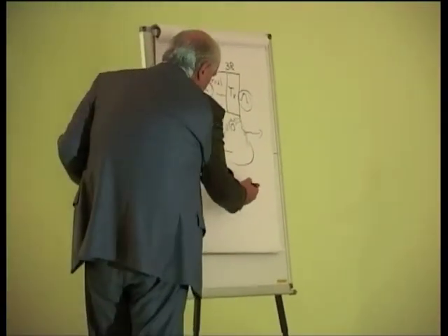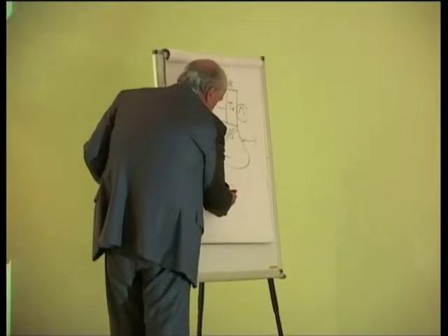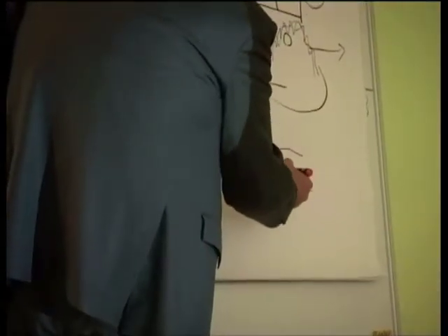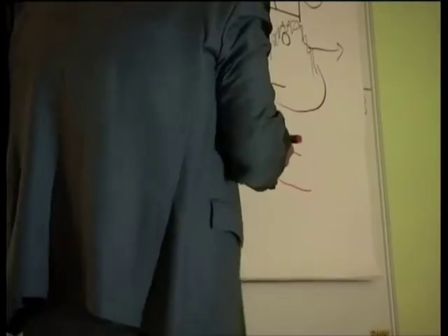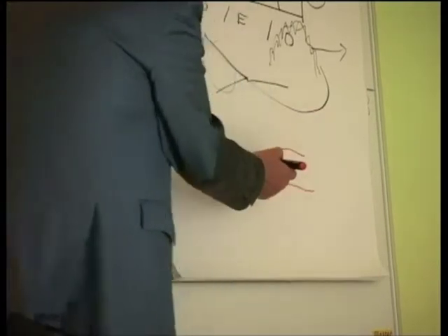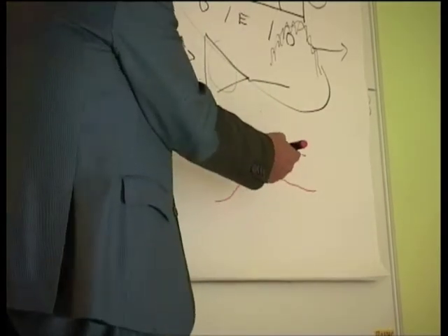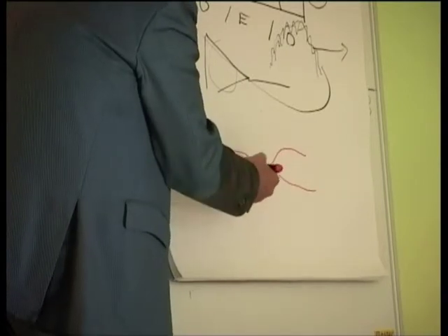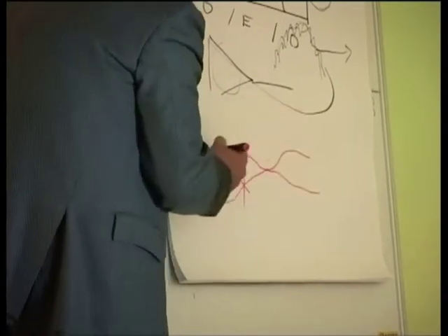I take two fibers, this is one fiber, this is the other one. I put the fibers very close with an electrical arc. I fuse this zone. I simply remove this part.